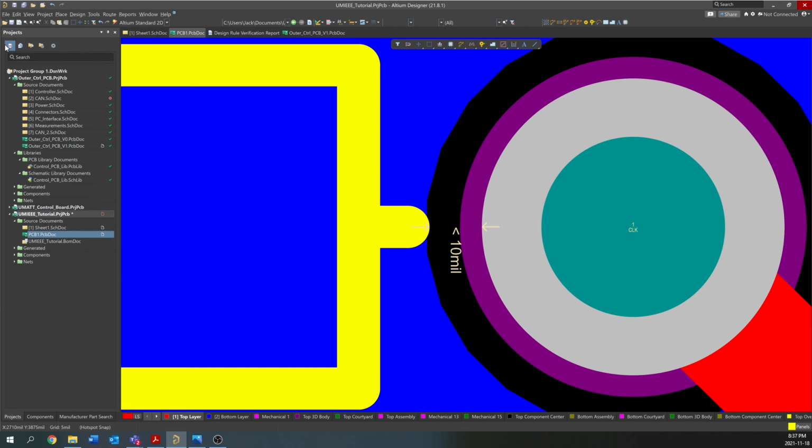A lot of the time, turnaround time is going to be the main thing. Most PCB manufacturers are about the same price range. For a small PCB like this, generally you have to order at least 5 copies. They won't do a run of just one. It's going to be like $2 for 5 PCBs, but then the shipping is going to be maybe $20 to $30 for that. So it makes sense, if you have multiple PCBs, to order them all at the same time.